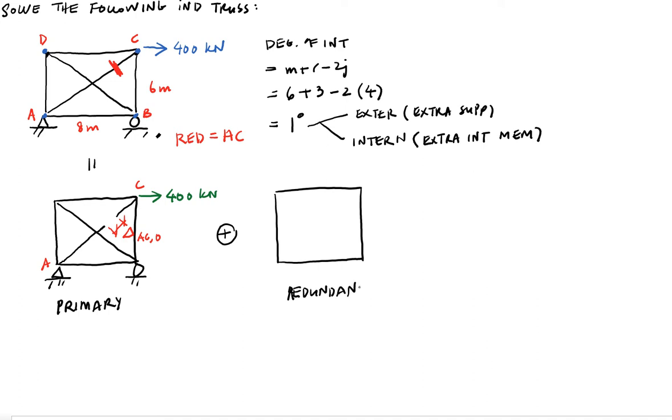And then as the method before, you then apply your redundant internal force. Your internal redundant would be the internal member AC. So what you do then, for member AC, you apply an internal force, FAC. Okay, pulling force means its tension. So because of this force, this member, you have cut it into two, so this member is going to overlap, and the amount is delta AC1, because of system redundant number 1.